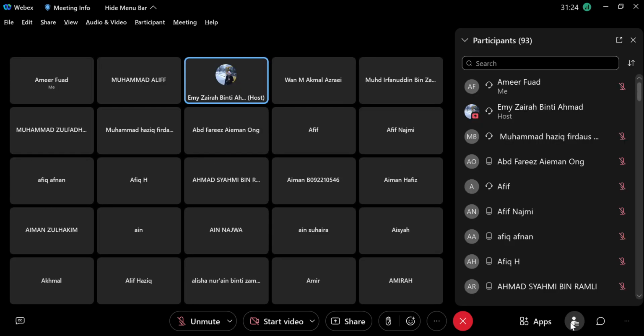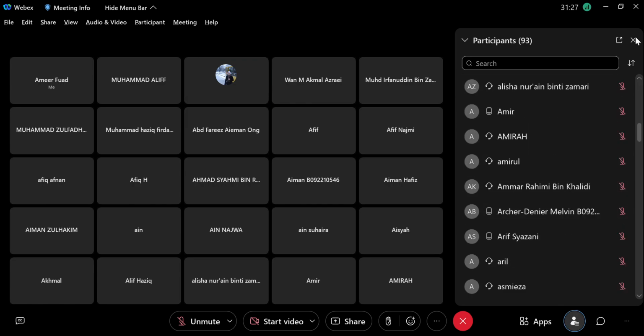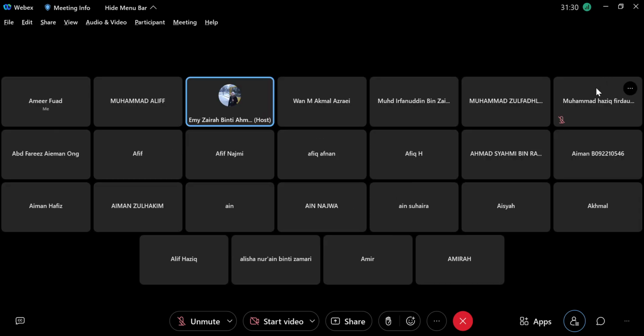Okay, now I want you to try to find, based on KCL here, as I previously explained, the inverting terminal. That's why this is the inverting terminal, and that's why it is called an inverting amplifier, because the supply is given to the inverting terminal. And then this is feedback.